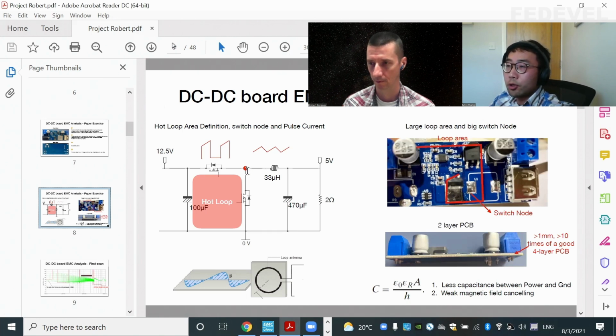That's what we call the noisy node. And as we said in the past, with an inductor you would be better off placing pin 1, the inside starting point of your winding, at this switch node, because then the outer layer will shield it.